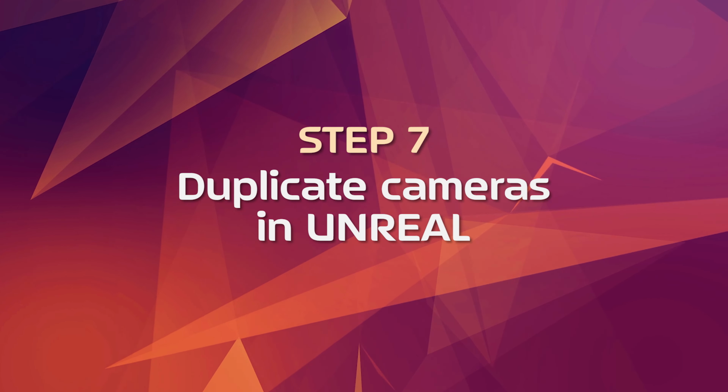Step 7. Duplicate cameras in Unreal. Now we need to duplicate this camera 3 times. In the World Outliner, click on UECam01, then press Ctrl D on the keyboard to duplicate it. Press F2 and adjust the naming to be UECam02.